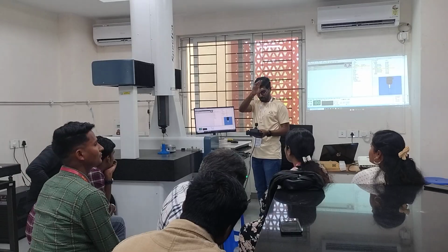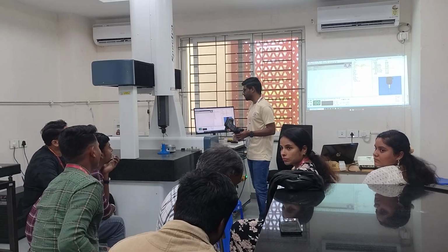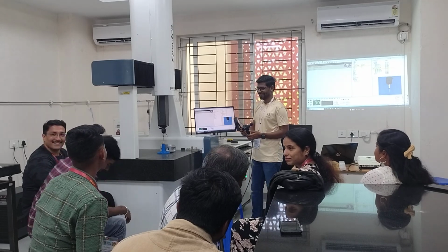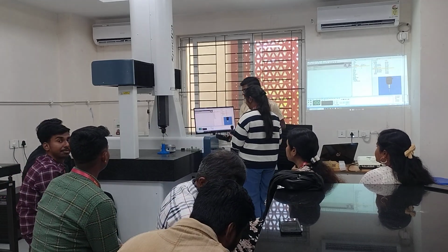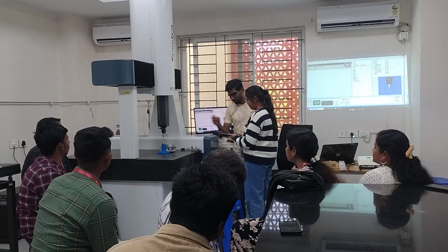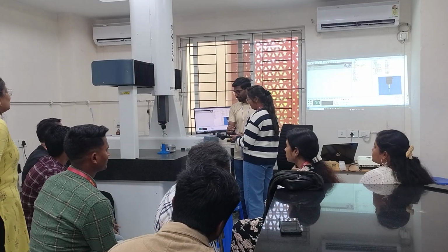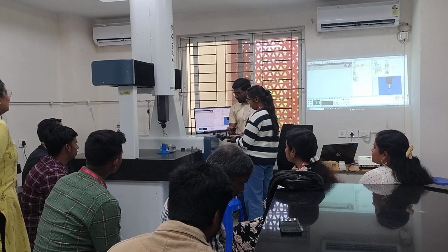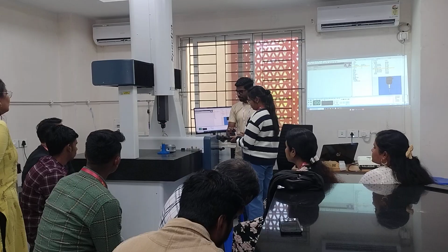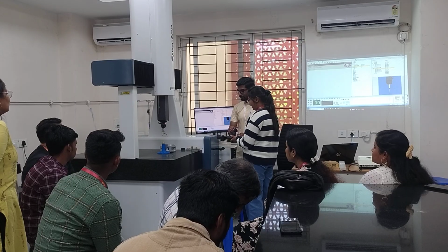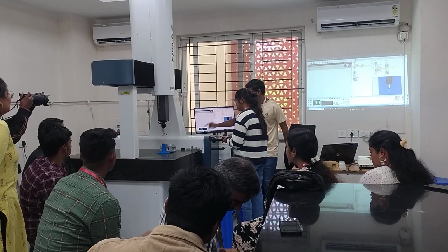Sangamitra, enough, you guys come, because the interns will have to learn. These people will live from here. So this plane you have to measure, okay? So this will go, lock. So this way it will go below. This way it will go up. Okay? Left, right, front, back. So on this surface, how many points do you have to take? 5 points. And the points will show you.